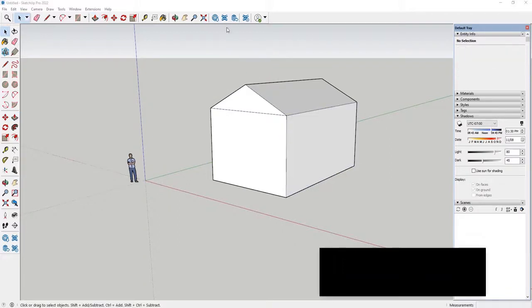Now we want to give this roof a little bit more profile so that it has some soffits and it'll be a little bit more massed on top of the walls than it currently is. So here's what we're going to do. We're going to go ahead and use the offset tool. Offsets, like we discussed in AutoCAD, are geometric displacements that are essentially scaled bigger or smaller versions of whatever shape we're displacing from. Let's go over to the toolbar here and select the offset command.